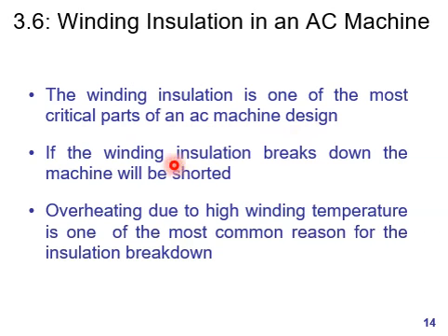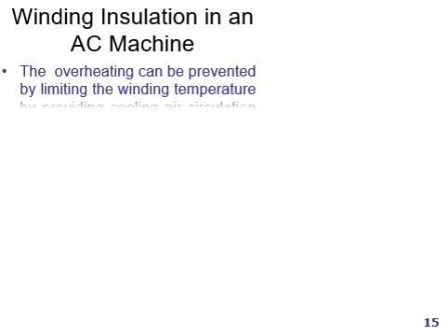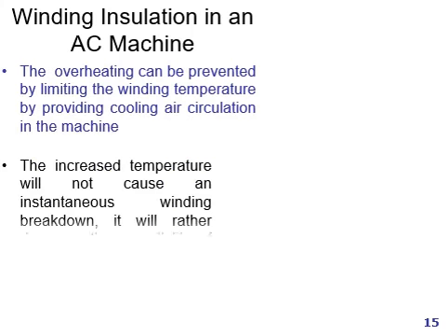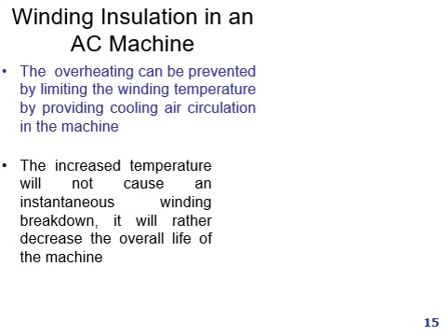If this insulation breaks down, the machine will be shorted. Overheating due to high winding temperature is one of the most common reasons for the insulation breakdown. Now we will know how we can prevent the overheating.